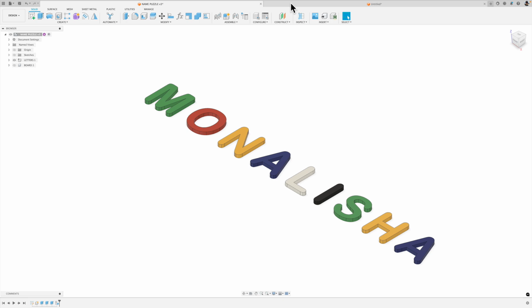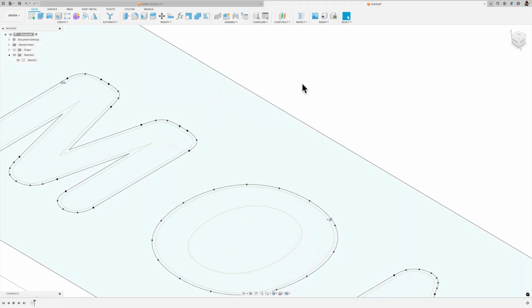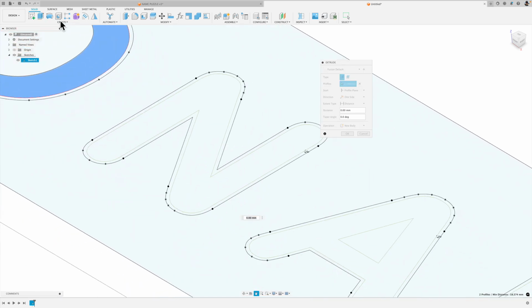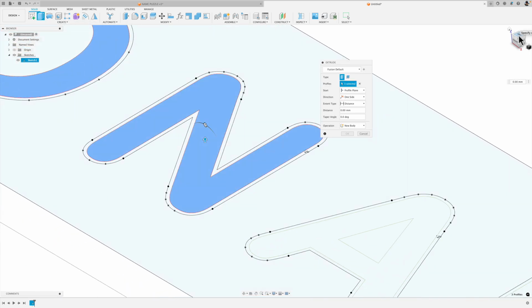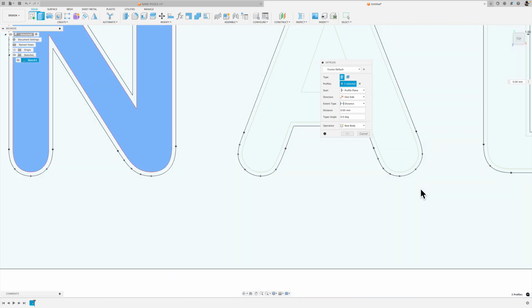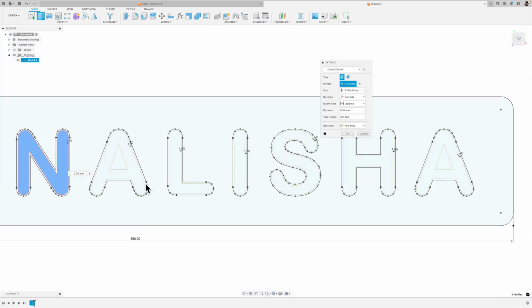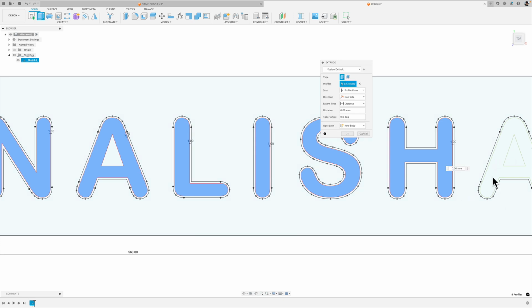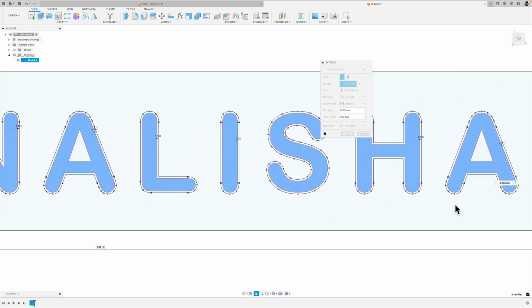Okay, so we'll go over here, and I'm going to make sure the extrude is active, and I'm going to click on the inside of the lettering. Alright, because we know that the offset distance is what we're pressing down into the board. So using my pan tool, I might switch back to this top view, zoom out a bit, and just make sure you're at a zoom distance where you can definitely see you're selecting the inside of the lettering. Okay, yep, that looks good.